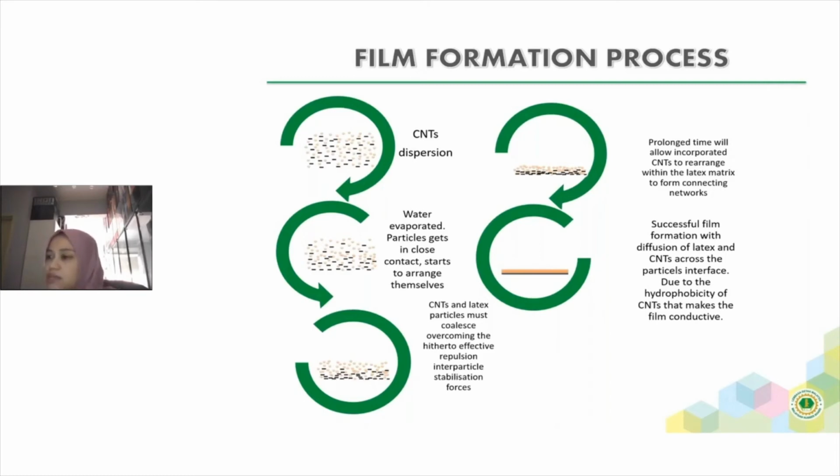Successful film formation is obtained by the diffusion of the latex and the carbon nanotubes across the particle interface. This is due to the hydrophobicity of the carbon nanotubes or the van der Waals forces, which makes the film conductive.